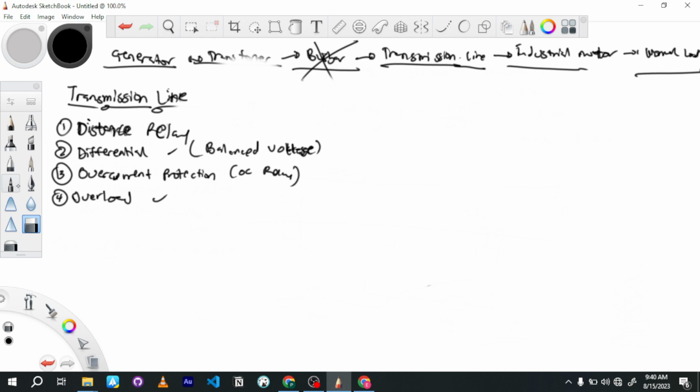And then heat equals I squared R T. So if, for example, I was drawing 400 A with 5 MVA, and now I'm drawing 410 amps, it's not so high an increase. But my system is still overloaded. What it leads to is that you get a lot of heat over time. So the more it goes on, the more your system becomes hot. It doesn't draw so much current that it can trip on overcurrent.